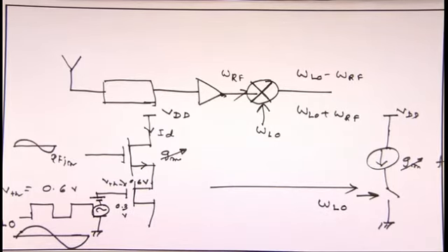What does it mean? That is, the modulation in the transconductance is now switched, or the current that is modulated is now being turned on and off. You are making some kind of switching in that current. So, essentially you have been able to convey the omega LO information to the changing current physically.